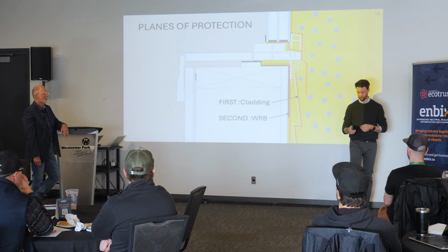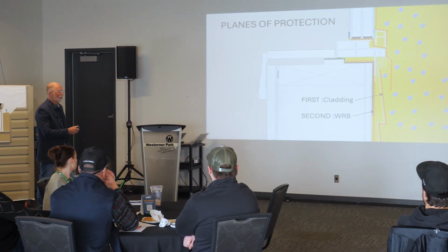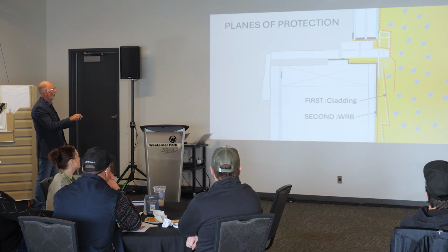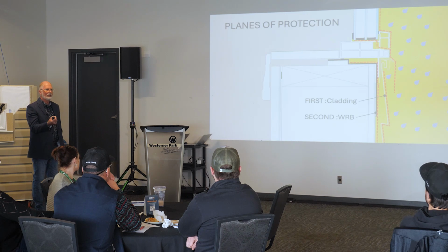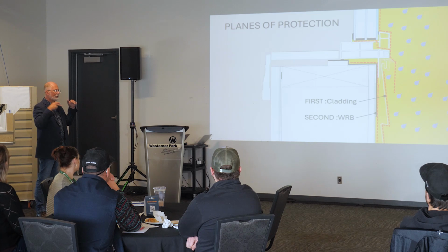Pretty common. Yeah. I think across the country, anything that I've looked at, that's the most common is spray foam around the perimeter. And it doesn't mean you can't insulate that bottom cavity. It just means be smart about the insulation you use. Like if you put a chunk of mineral wool in there, extremely drainable material.